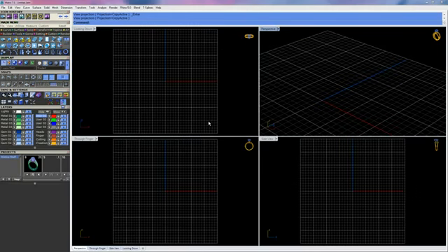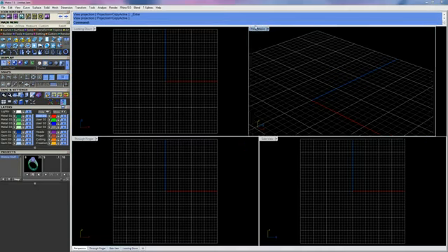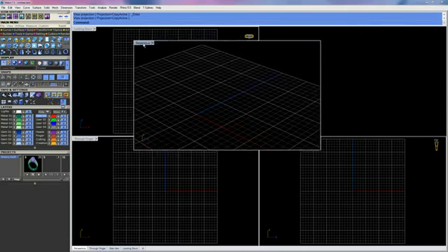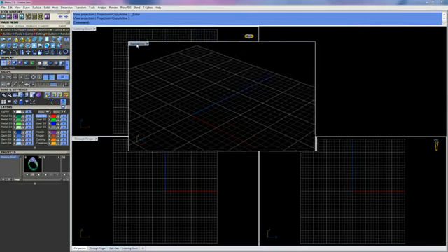So one of the other new viewport features within Matrix 7.5 is that if I click and drag on the perspective viewport, for example, and this is going to be hard to demonstrate on one single screen, but if I were to drag this off screen, or you can see I'm placing my cursor over my menus, as soon as I do that, it creates a copy of my existing perspective viewport. So I can move this over to my second monitor, for example, if I'm using a two-monitor setup. All right, so we can X out of that.